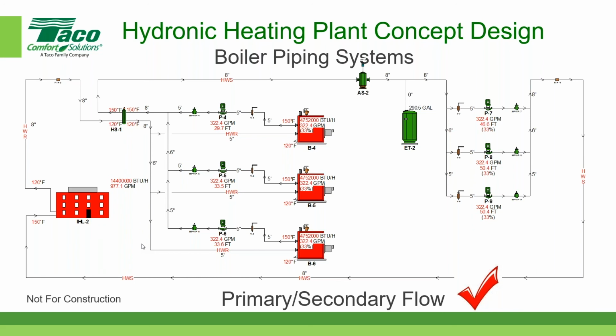So one of the issues has always been in our industry is that the more energy efficient the system, ultimately that translates into more surface area, more material, and more first cost. And so that's where the whole economic analysis comes in, in terms of trading off the temperature differentials against the additional cost for terminal devices and perhaps additional cost with boilers in order to accommodate those high delta Ts. The trend today is to go in the range of around 25 to 30 degrees. Although, I think I've seen designs where people are using 40 degrees, but you have to pay attention to the details and not box yourself in.